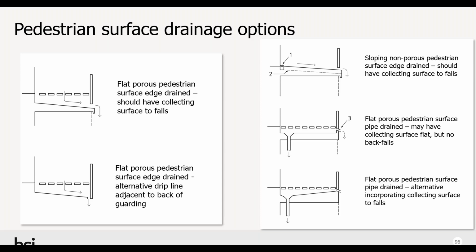It's also important to consider cumulative flow and downpipe design, if water from one balcony is drained down onto another balcony and collecting water from that on its journey under gravity down to ground level. That's frequently encountered. And furthermore, the warning pipe design, next slide please.